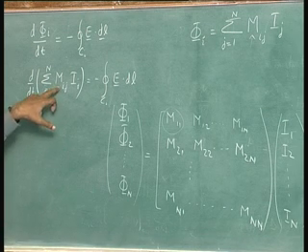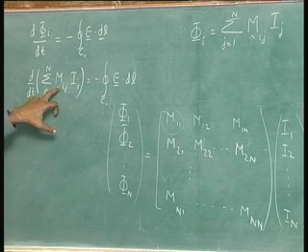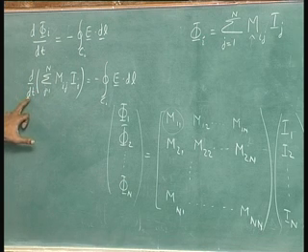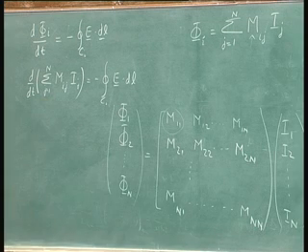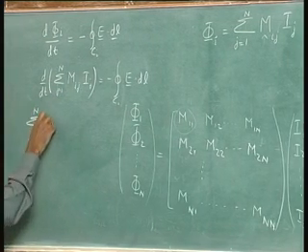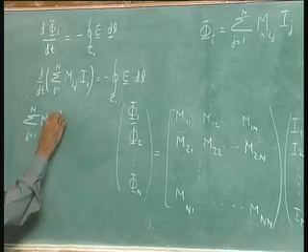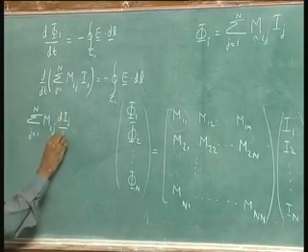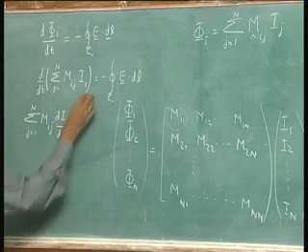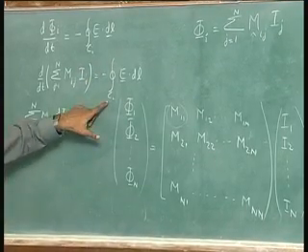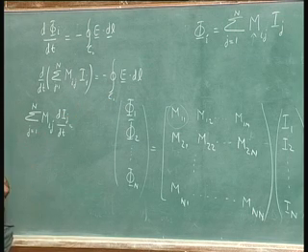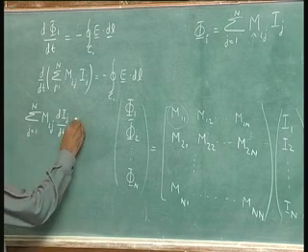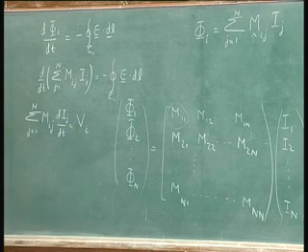Now, let us assume that these coils are stationary, moving coils will come later. So, then d/dt does not affect capital M, it affects only capital I. So, you get the sum over j equals 1 to capital N of M_ij dI_j/dt is equal to, now what is the loop integral of E dot dl over C_i? It is nothing but the induced EMF. So, it is equal to V sub i.